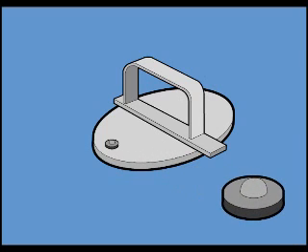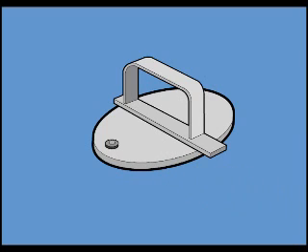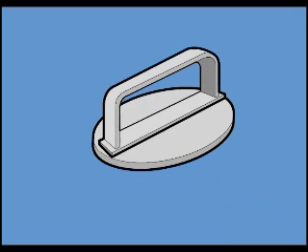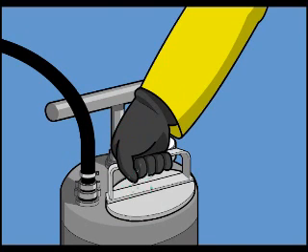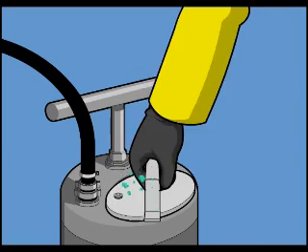Having checked the sprayer, depressurize by rotating the lid handle so that it stops on top of the pressure release button valve on top of the lid. During this process, hold the handle to prevent the lid from falling into the tank. Empty the clean water you have used for testing the sprayer.